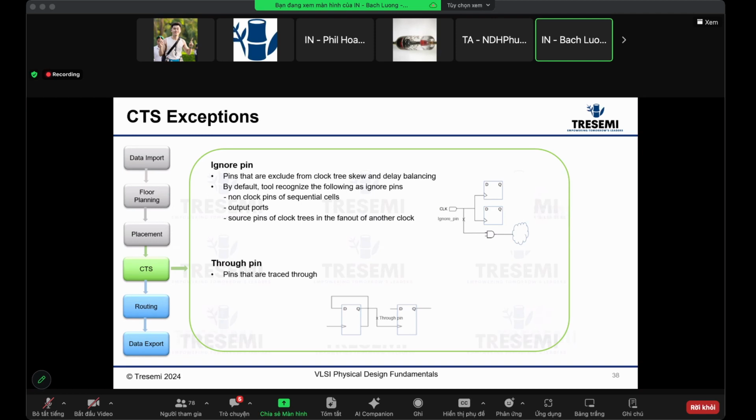Phil, just a side question, do you normally use ignore pin or exclude pin? I seldom do these things, but occasionally we really don't define them until the logic guys tell us. Most of the time they are automatic. In some cases, yeah, you use ignore pin to do certain types of weird logic.